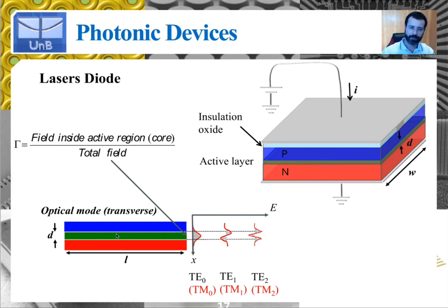And these sorts of waveguides have transverse modes, right? So you could have the TE mode, fundamental and higher order modes as well. But in optical waveguides, as opposed to say microwave waveguides, only a fraction of the electromagnetic field is inside the core of the waveguide itself, right?